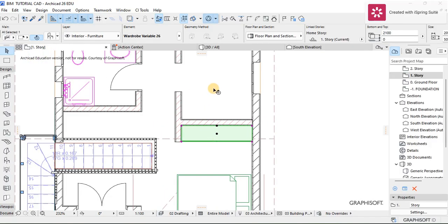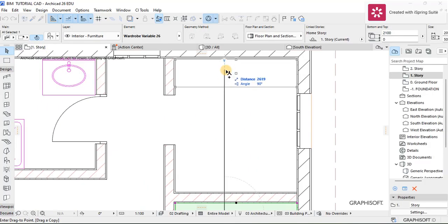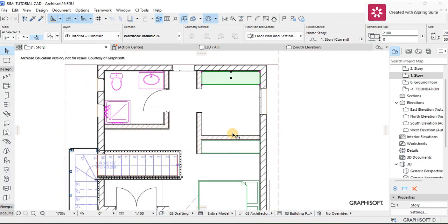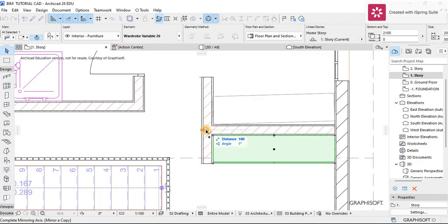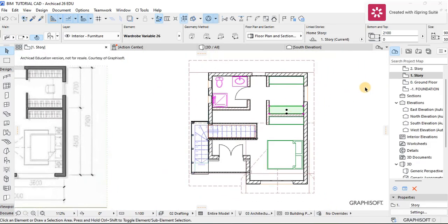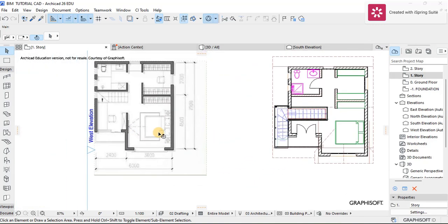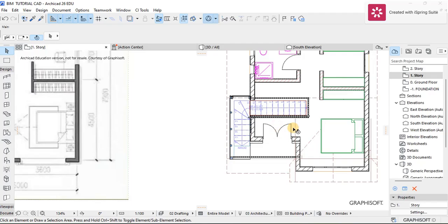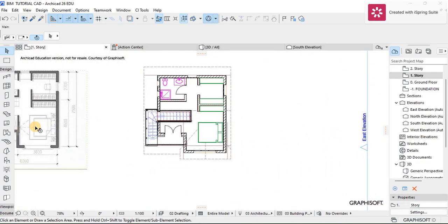And with that done, I want to drag the same instance to this place here. So I'm going to Control Shift D to drag a copy to there. Then with that done, I'm going to mirror this copy on the other side. So Control Shift M, and then I'm going to mirror it on the center of this wall here. Yeah, now we have done our wardrobe, and the next thing, I think what's remaining, most of the design changes we made will not allow for me to have some furniture on this area here.